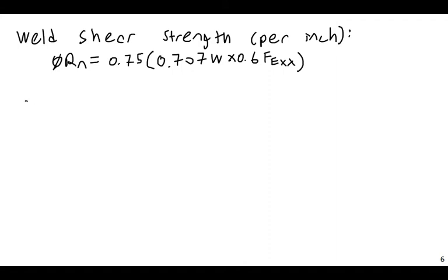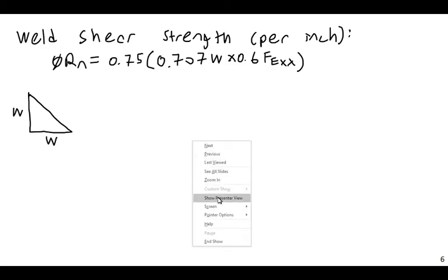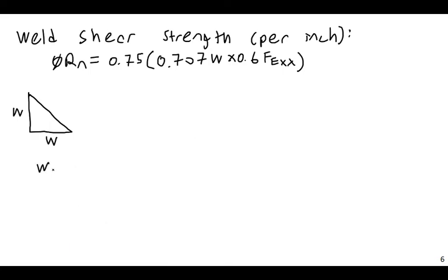First of all, W is going to be the width of the weld. This would be its narrowest dimension, but we're assuming a 45-degree angle here. I'm assuming a weld that is an isosceles triangle here. If we don't have that, then we would need to adjust this. But basically, if you think about this, what does this mean? Well, first of all, let's just annotate this.